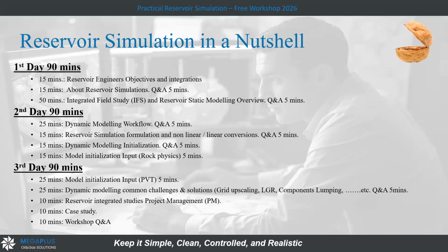I don't need to put a massive number of curves, only one curve that will be normalized, and then the model will denormalize again, and depending on the endpoint scaling, the model will distribute the relative permeability curves again for each rock type or each lithology that we have in facies modeling. And finally, we discussed the interfacial tension and how it affects the wettability and the capillarity in the model.